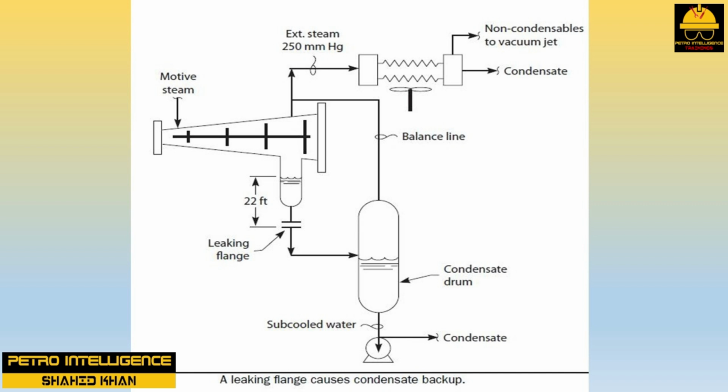The turbine case pressure was increased by raising the pressure in the air-cooled surface condenser. This was accomplished by shutting off several of the air fans, which, in turn, increased the condensing temperature of the exhaust steam. But why would raising the turbine case pressure drain the turbine anyway? After all, increasing the surface condenser pressure also increased the pressure in the drum that the turbine case drained to. The answer is revealed when the available data are converted to consistent units.